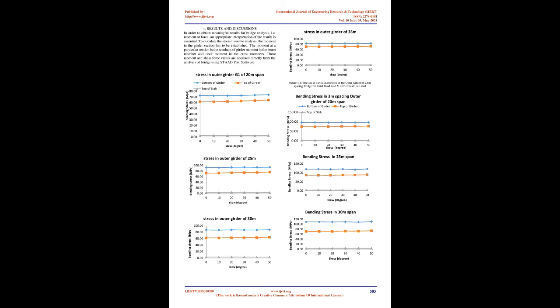When a bridge deck is analyzed by the method of grillage analogy, there are essentially 5 steps to be followed for obtaining design responses. 1. Idealization of physical deck into equivalent grillage. 2. Evaluation of equivalent elastic inertia of members of grillage. 3. Application and transfer of loads to various nodes of grillage. 4. Determine force responses and design envelopes, and 5. Results interpretation.